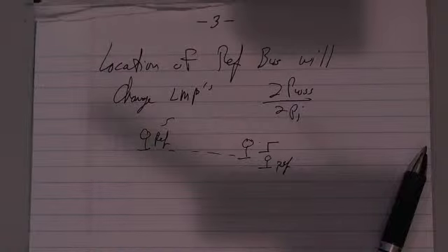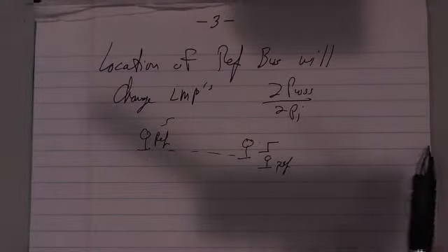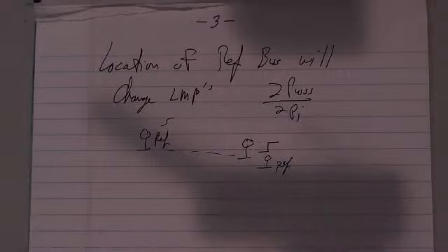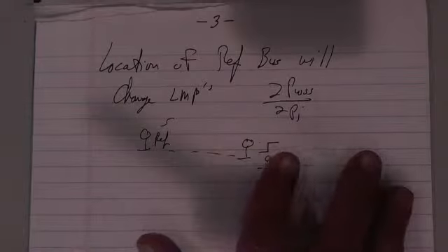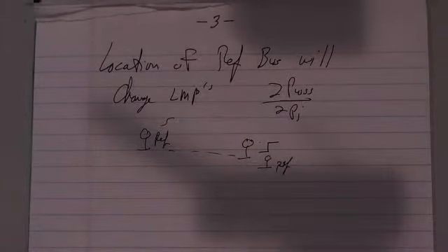He said we need some way to separate marginal loss revenue from congestion. We use a load weighted average of all buses as the reference bus. So they have a way of deciding what the bus is. I'm not sure what he means by load weighted average, but they have a way of averaging that over the whole system. Congestion revenue gets paid out.